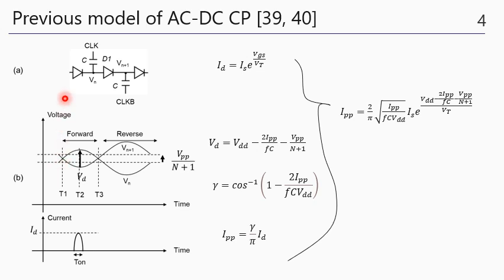And here's the Vn and Vn plus 1. Because the DC between the two should be expressed by this, because we have n plus 1 diodes between the input to PPP, and this voltage difference we call VD, the diode voltage, can be given by this equation, where IPP is the average current, which is the same amount of current that flows through every single rectifier.